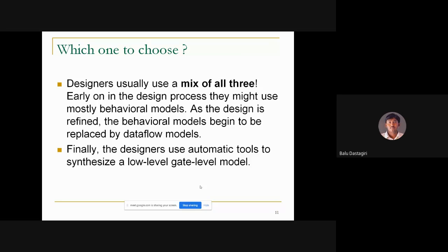If we are using the same type of functionality, it may be a little complex or it may be high in area, so more number of gates will be used. For example, in the ripple carry adder, if you describe each step of the internal connections, more number of gates will be there. Once you get to the full adder design, if you directly specify it by using the equations, it is very easy. Otherwise we have to define the half adders again, and all this stuff will be there.